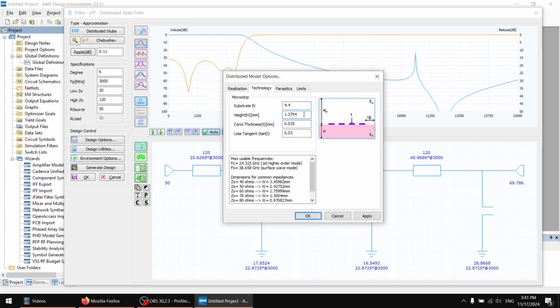With 1.6 millimeters, you can see right here, because it has some calculation given for us, this will be a 3 millimeter wide trace. This is very thick. For 1.2, we are talking about 2.4, I think 2.28, so close enough. If you have a special substrate with 0.6 millimeters, this will be about 1.13, right?